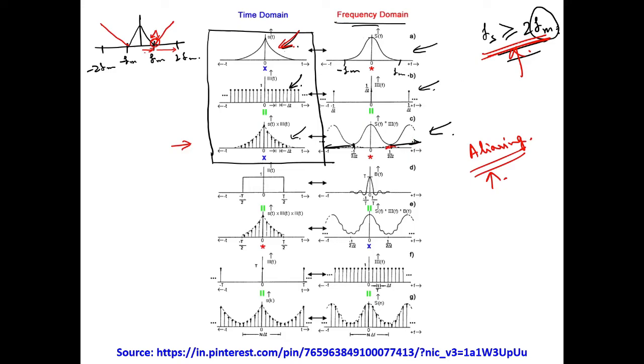However, I told you, when we were sampling, we did the band limitation in the frequency domain. Similarly, when we want to do sampling in the frequency domain, we need to time limit the signal. That means within a specific time, we need to restrict our signal component.